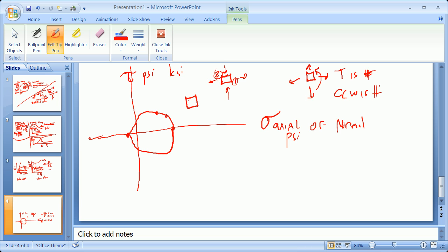So while this may exhibit itself like this and like this and like this and like this, when you go ahead and did that at some degree here, you would have some shear going across, and in this case the shear would be positive on one face, on face 1 positive, which would be this way, and negative on the other way. So what you most want to grab is that you graph two types of stress with the same units on this, what is called Mohr's circle of combined stresses.